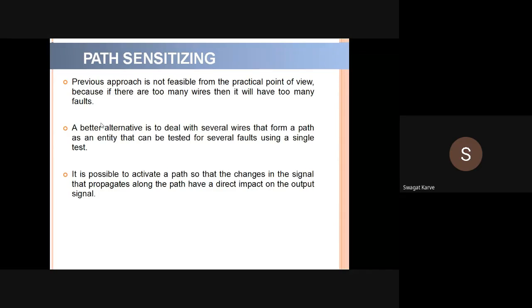So, combinational logic testing has three methods. First one is the stuck-at fault, then path sensitization, and third one is random testing. Coming to sequential logic testing, it has boundary scan test, built-in self test, right? Then JTAG, that is nothing but boundary scan. So these are the different methods available for sequential logic testing. We have covered the stuck-at fault model. Now today we will discuss path sensitization.